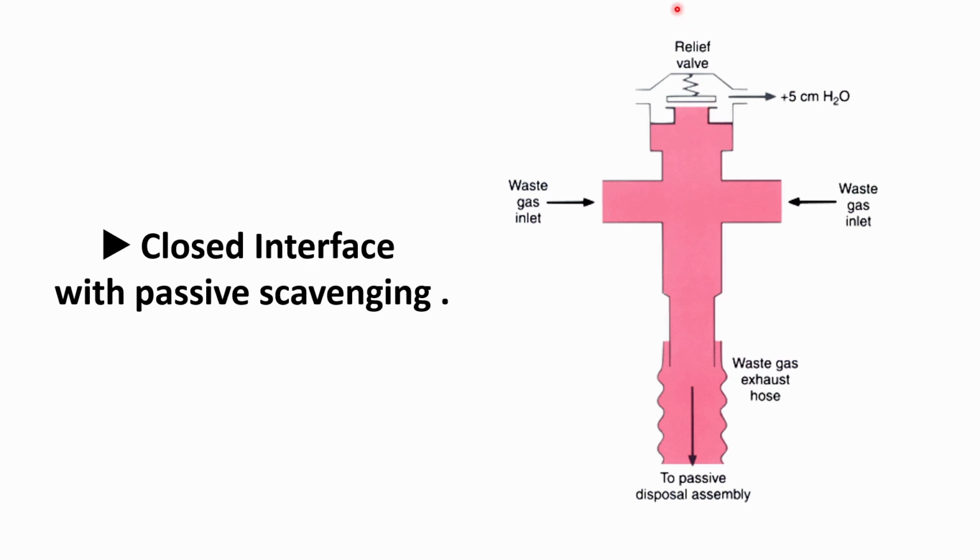No, it will apply a positive pressure here to a relief valve which will open at 5 centimeters of water, and it will give a chance to allow the maintenance of this system before starting the next patient, because this valve is connected to an alarm, and this alarm will have an audible sound or a light, so it will allow us to see a problem, and after that it will allow us to maintain and repair this error, and it will have less impact of pollution than having these gases inside the OT.